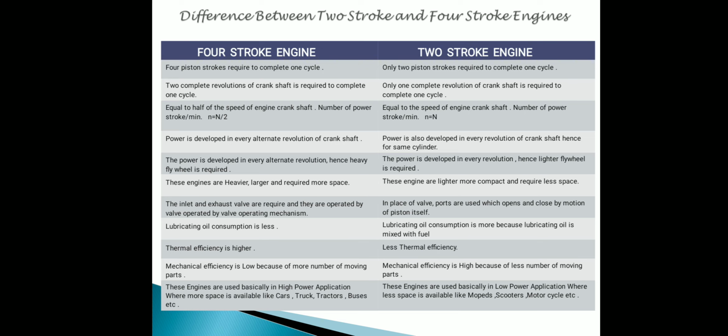In the four stroke engine, valves are necessary. Thermal efficiency is higher for the four stroke engine and lower for the two stroke engine. Mechanical efficiency is low in the four stroke engine because of more moving parts, but in the two stroke engine mechanical efficiency is high because of fewer moving parts.